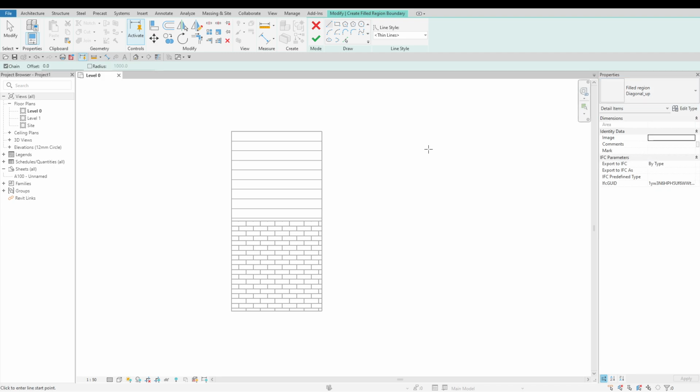Next, in the ribbon, open the Line Styles drop-down to choose the boundary style that best fits your intent. Selecting the right line style is crucial for maintaining drawing clarity and adhering to BIM documentation standards. Below are several commonly used line styles and their typical applications within the AEC environment. The Beyond Line style is used to represent elements that fall below the primary view range of a plan, specifically below the bottom plane, but still within the defined view depth. For example, wall foundations are often illustrated using the Beyond style to distinguish them from elements at the main level.